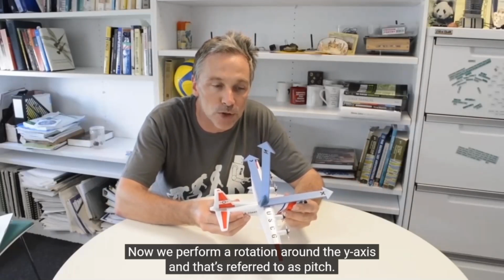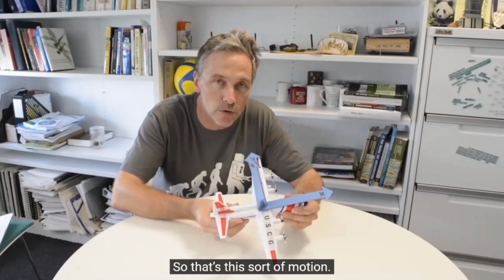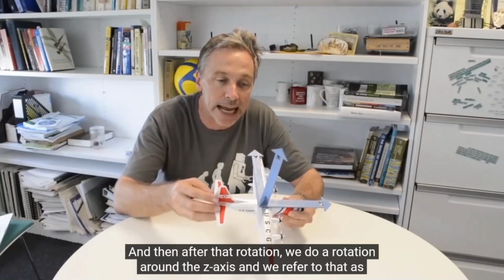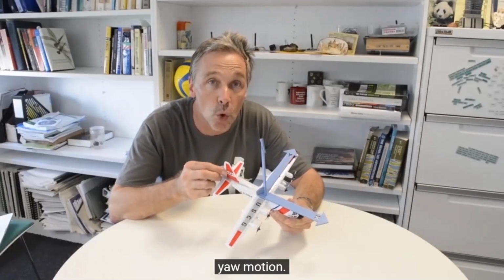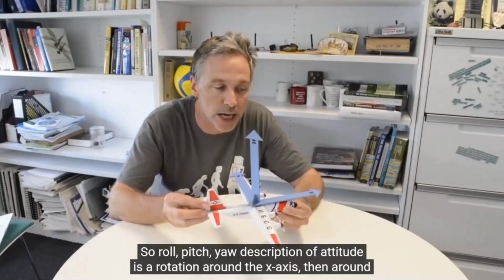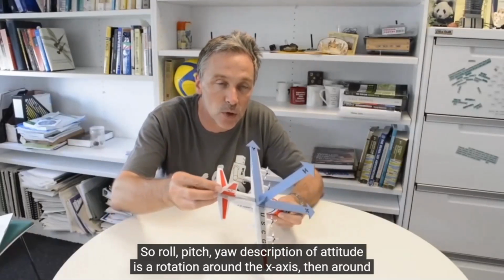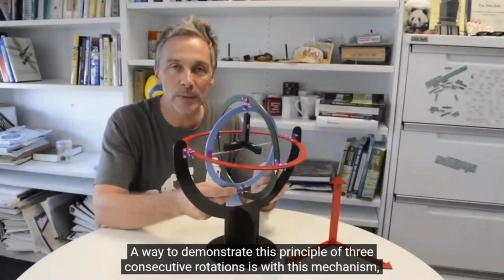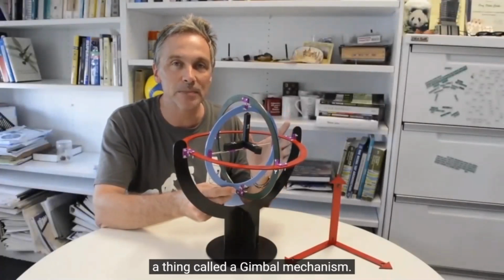And then we perform a rotation around the y-axis, and that's referred to as pitch. So that's this sort of motion. And then after that rotation, we do a rotation around the z-axis, and we refer to that as yaw motion. So roll, pitch, yaw description of attitude is a rotation around the x-axis, then around the y-axis, and then around the z-axis.